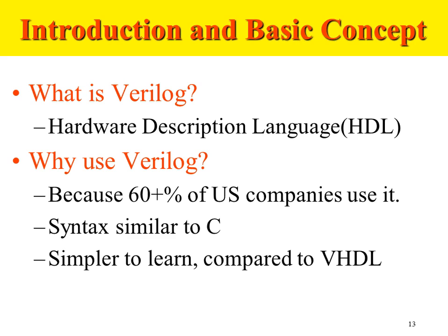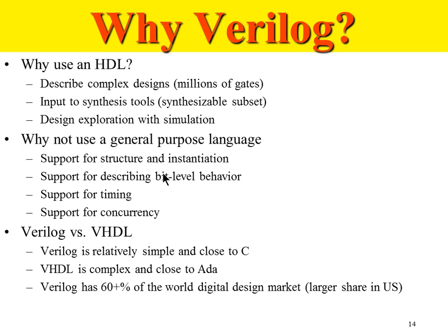It is a very strongly typed language. So learning VHDL is comparatively more difficult than learning Verilog. In Verilog, the syntax is more similar to C, and it has more flexibility in the way the language is defined. So it's easier to learn Verilog. That might also be one of the reasons why the usage of Verilog increased over a period of time. Nowadays in the industry it's mostly standardized to Verilog. Very few teams will still use VHDL, but that will be a very small percentage. Mostly it is Verilog in the industry.